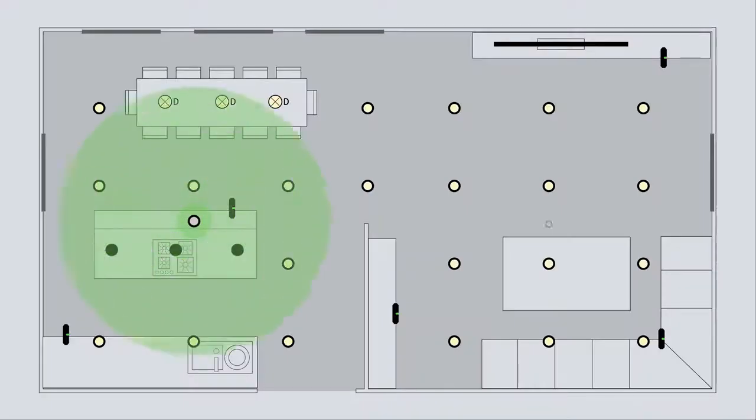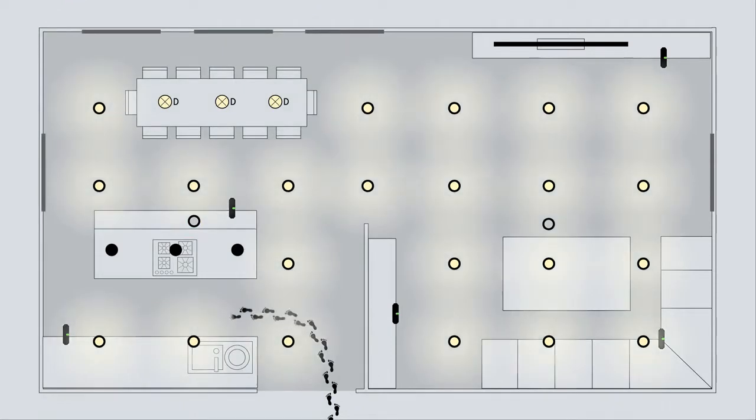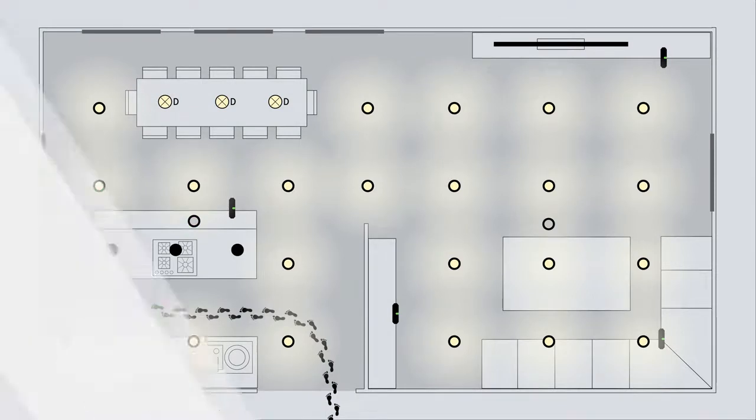Firstly, we believe that if something can be done automatically, it should be. Presence sensors can reduce the need for manual lighting control in many rooms. Through precise presence detection, including brightness measurement, the mini server can decide whether ambient lighting is necessary. For example, ambient lighting is automatically activated if the current brightness levels are below a set threshold.